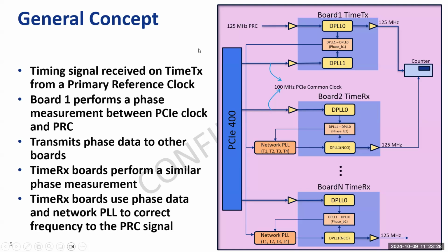One thing, Greg, I'm just wondering again, for the frequency it should not make a difference, right? When it's with spread spectrum, because you're looking for the differences. For the phase, you're right. That's why I was highlighting that one of the limitations I see is if you're doing a phase measurement between two clocks, and if they are themselves fairly jitter-free clocks, you're right. What you're showing here is valid and can be done.